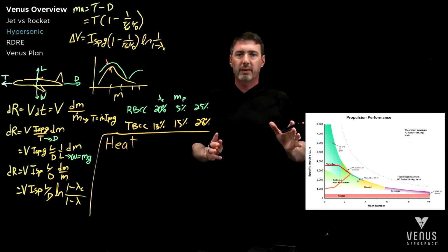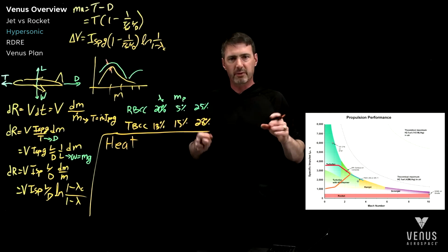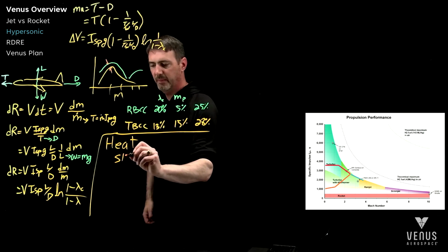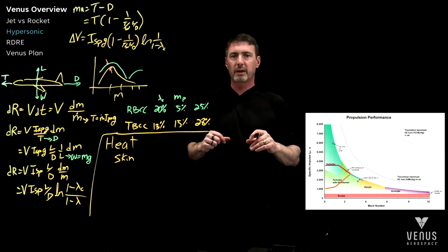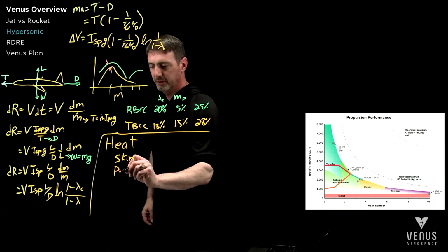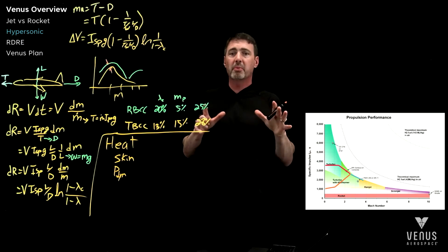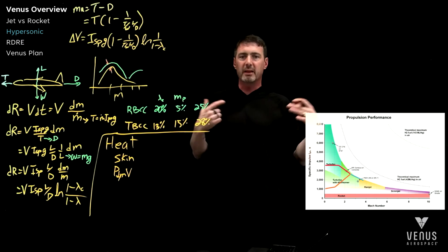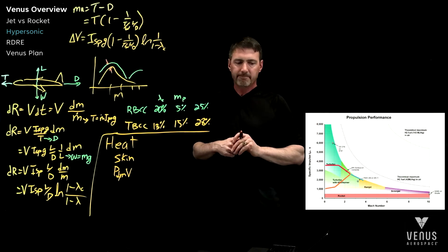And there are really three versions of heat. In that first overview, I was really just talking about skin friction just to give you the idea behind all of this. And so, there's skin friction. And if you remember, we had said that skin friction was roughly, the heat energy was roughly that dynamic pressure. So whatever pounds per square foot, or whatever your dynamic pressure the aircraft is flying at, times the velocity. Now, that gets radiated away at T to the fourth.